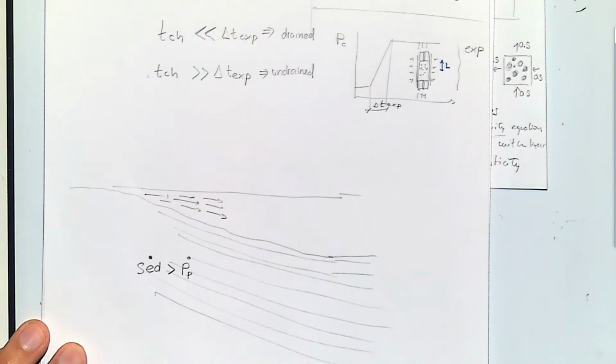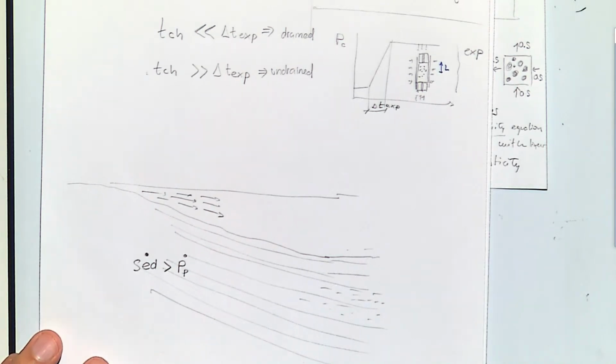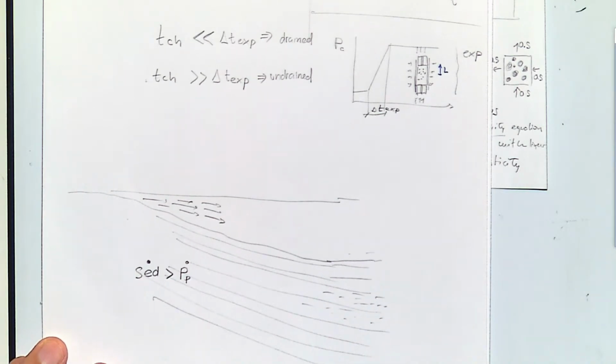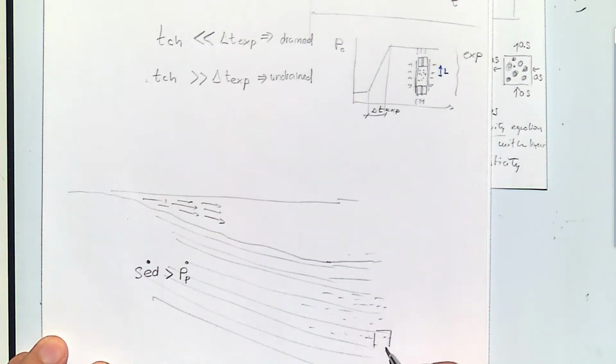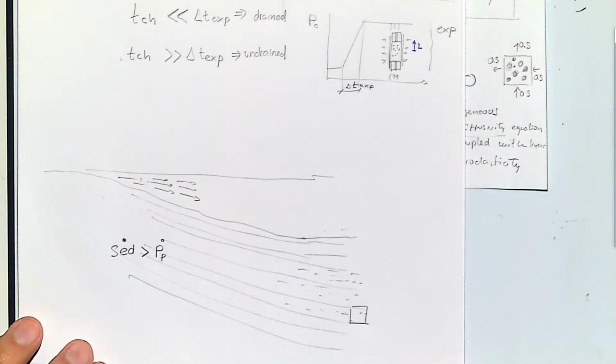And when that happens, because probably here you're adding lots of sediments, they pile on top of each other, some of those sediments may have a low permeability. If you're just piling up sands, you're not going to have any buildup of pore pressure. But if you're piling up silts with clays, and those are sediments with low permeability, the result of that is that in some of these layers, in some of these sediments, the pore pressure may be still locked in. I mean, it may be diffusing with time.